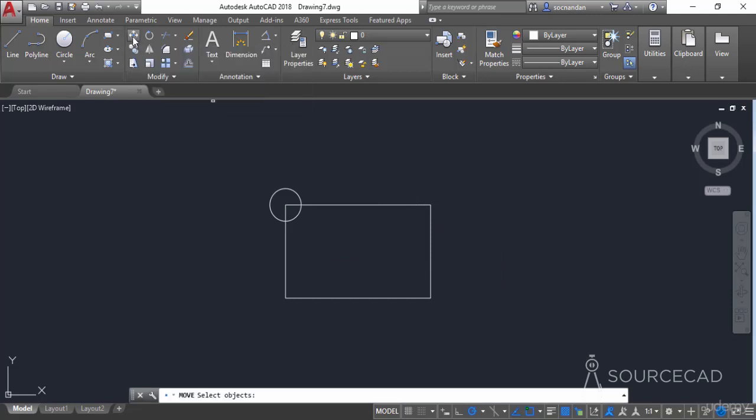So select the move tool. Now click on the circle, press enter, and now specify the base point. As you can see here, the command line prompts you to specify the base point. So the base point will be the point from where the object will be picked. Now click here and you'll notice that the object will now move along with our cursor.